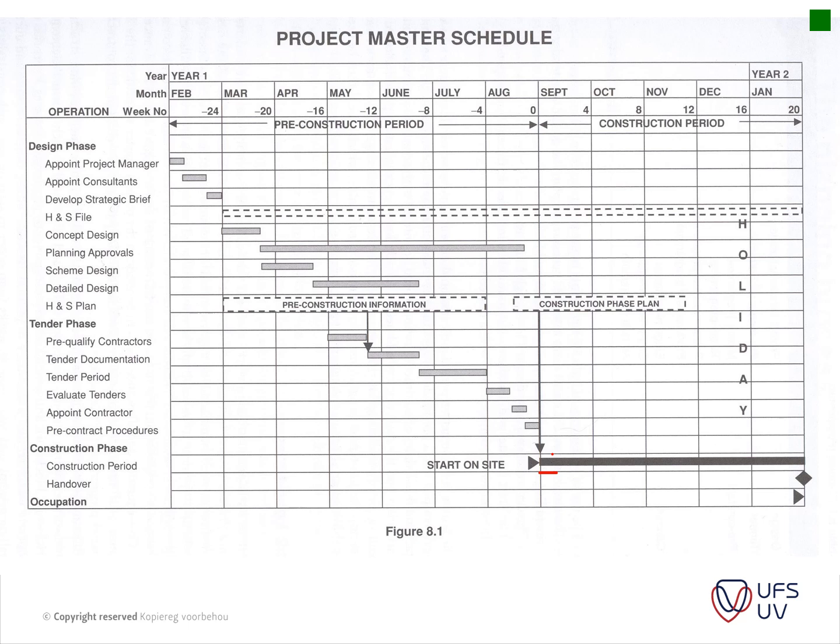So it's solely one line, and this is now the consultants basically saying, okay, if it's for instance a 3 million rand worth of project, a contractor of this size might be able to spend about 500,000 per month, or claim 500,000 per month. So thus he will need about 6 months to complete this project, and that's that one line, and that's calculated like that. So it comes with a bit of a sum sense and a bit of experience to actually calculate that type of thing.